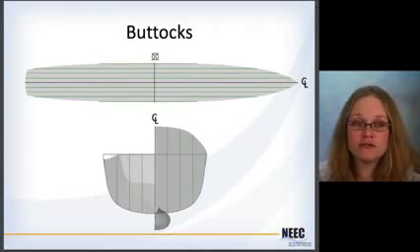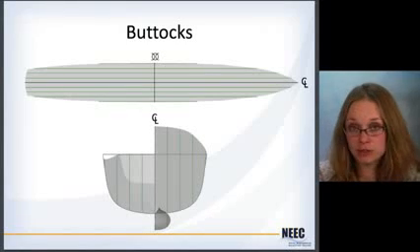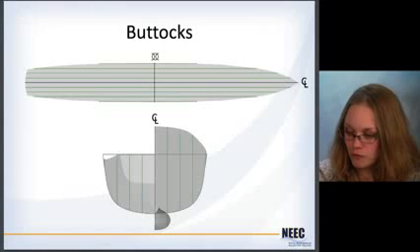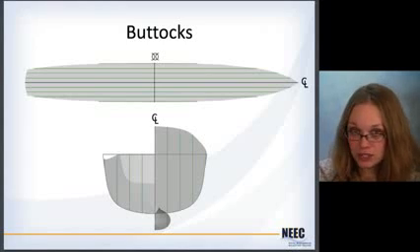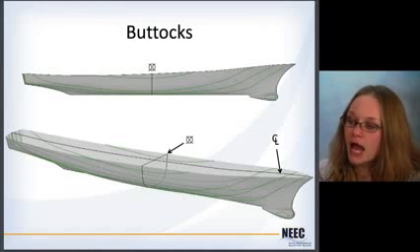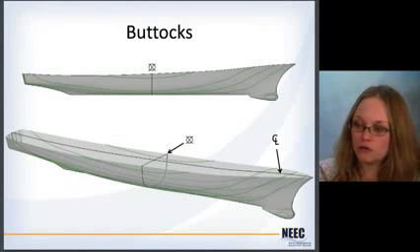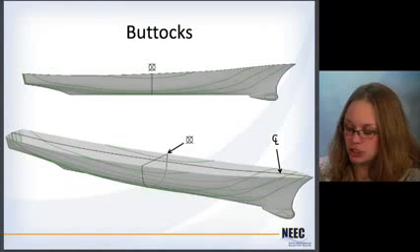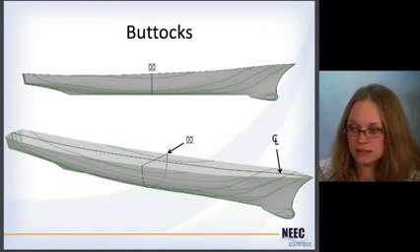Finally, if you take the centerline plane and take a bunch of copies and send them port and starboard, you get what are called buttock lines. Again, from the top and from the front or back view, you get straight lines. But if you look at it from the side or from this oblique view, you start to get these contours as you go from port to starboard, or left to right. So now you can see how the ship's hull is changing from side to side.